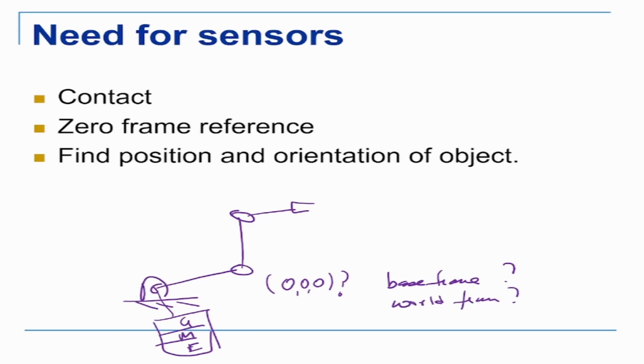So what it does is, when you switch it on, it does a motion which is called homing or calibration. It will move to one side, and if there is a limit switch there, and a limit switch is something like a normal switch, then if the link hits or touches that switch, it immediately knows that that's the 0 of the system. That is one.